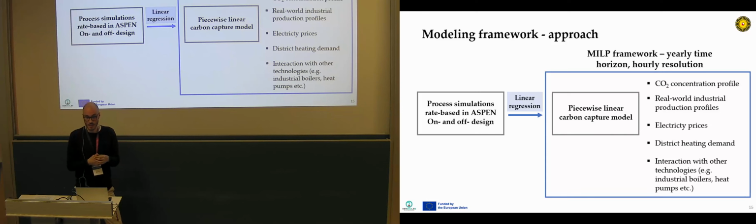Now, once we have the piecewise linear capture model, we can embed it into a bigger MILP framework, which has a yearly time horizon with hourly resolution. And in this framework, we can have things like the CO2 concentration profile over time, the real-world industrial production profiles, the electricity prices, district heating demand, and also importantly, the interaction with other technologies. So for example, if we have industrial boilers or heat pumps or anything else.